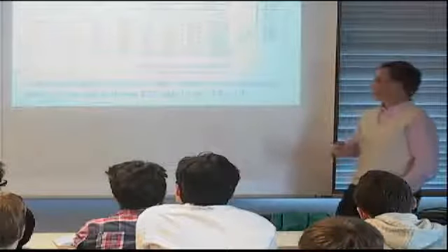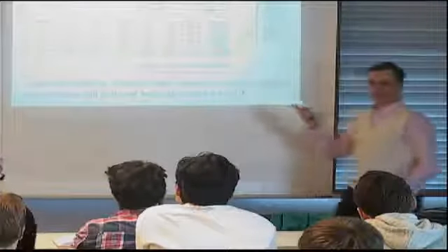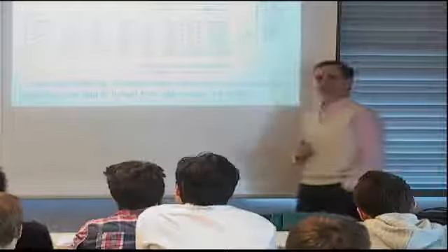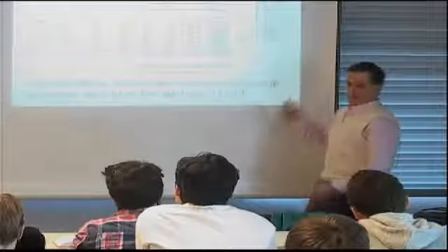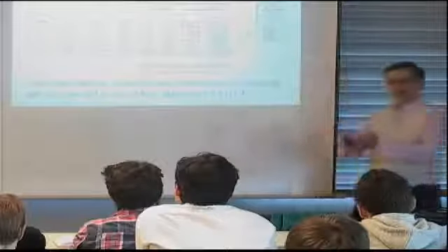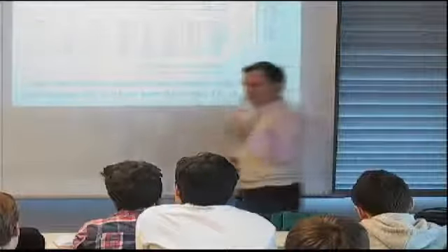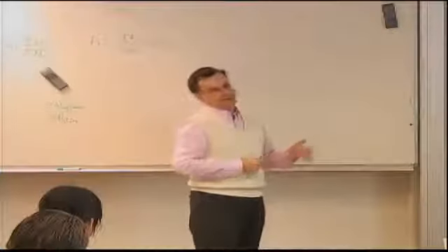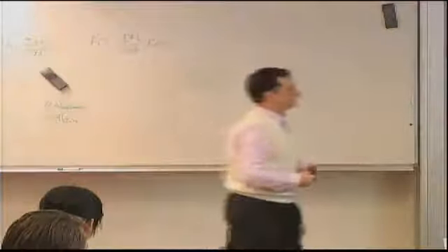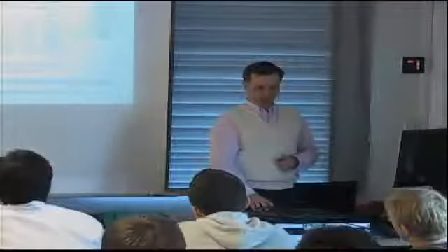So conceivably, you could take some of the load from the skin, say, okay, I'm going to allow it to fail, and any extra load will go to these guys according to their own EAs. And if I show that it doesn't fail, I can claim that while I do have first failure at that applied load, that load can be redistributed to the stiffener, and that would be sufficient. That's one way. May not be the best, but any approach to improve this design is up to whoever wants to think about it.